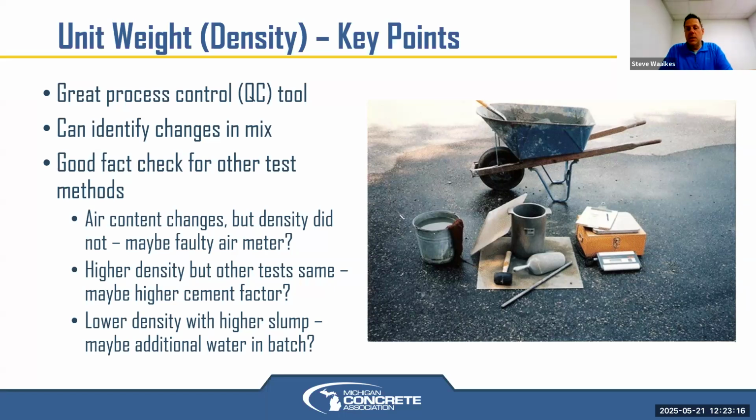And all it requires of technicians in the field is that when they're doing an air pressure meter test, they strike it off with a plate instead of a bar, and that they also have a scale in the field and just weigh the bucket, write the weight down, and figure out the density calculations later on. If they've got the same bucket all the time, they just measure and write down the weight and see if the weight of that known volume changes over time.